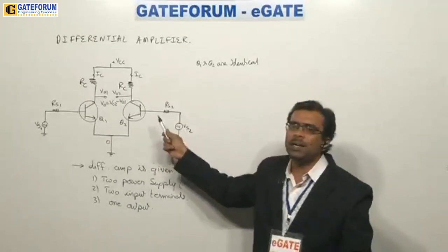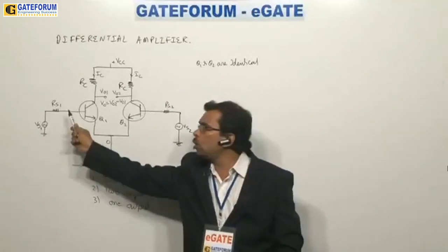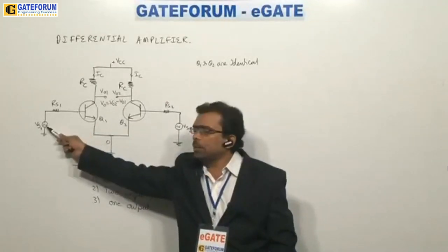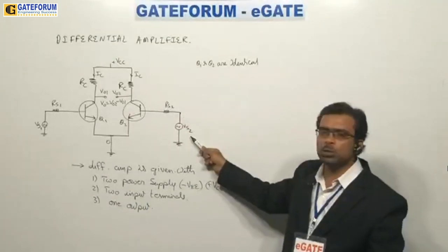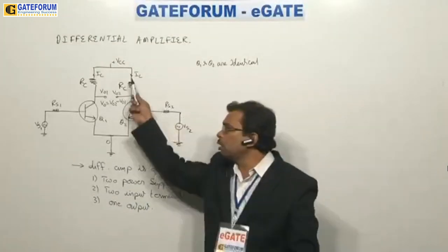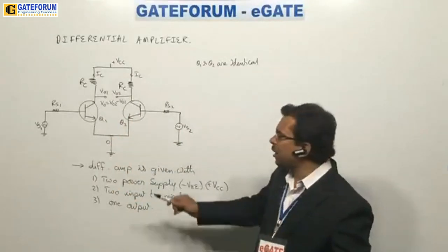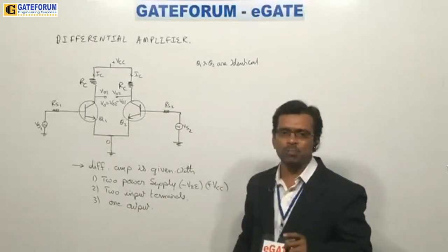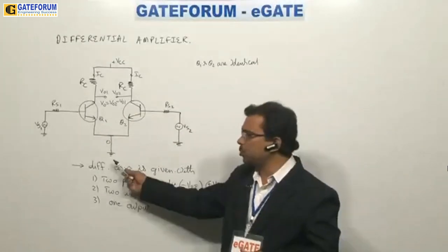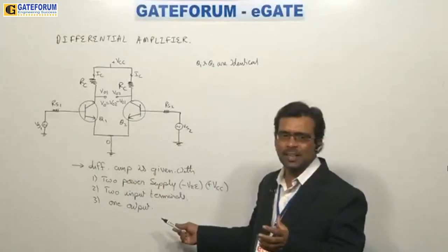And this is the source resistance and this is the source resistance. The op amp is nowhere linked to this. So now you can understand that this RS1 belongs to the source, and RS2 belongs to the source. So don't worry about this point. These parameters are kept constant. Now, why do I need to connect minus VEE? Earlier we were connecting only one source, plus VCC. We did not connect minus VEE here, but now we are connecting this, isn't it?